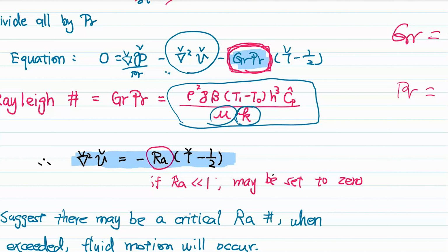The thermal conductivity: if you have a higher thermal conductivity, that means the temperature gradient evens out faster. So you won't have such a large temperature gradient to cause the density difference. Okay, so that also makes sense. So a very viscous fluid with fast conduction or high thermal conductivity is not going to favor free convection and will be more stable.